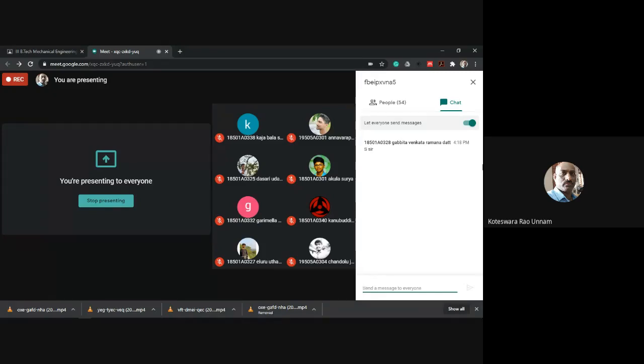Therefore you have two diameters, and that's why he has given two things here. D dash is the nominal diameter of the rivet, that is, the diameter of the rivet before riveting, which is generally expressed in mm. Then you have D. D is the gross diameter of the rivet, that is, the diameter of the rivet after riveting. So your D dash is less than D, and the relation is D dash is D minus 1.5. You need to take it like that.